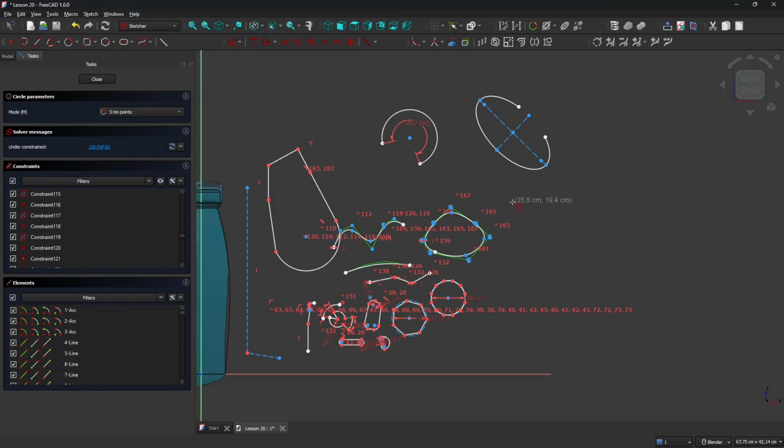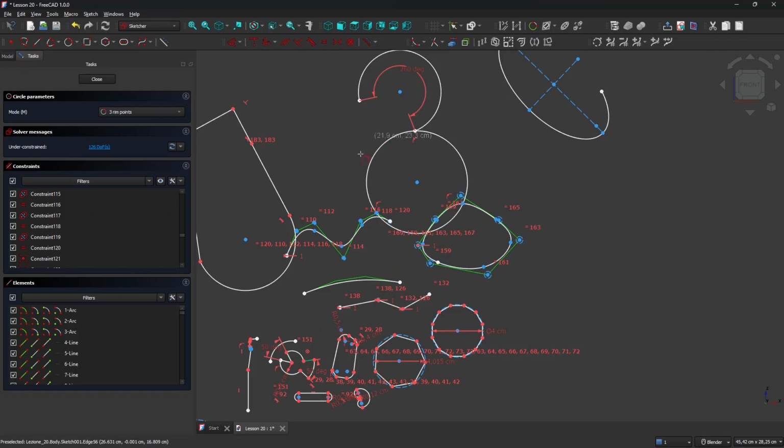Sometimes you have different ways you can create objects, and perhaps you can snap to other points. So if I click here and click here and click here, this is a 3-point circle creation. So creating a circle by 3 points is a little bit different. And again, you have the ellipse or the ellipse by 3 points.